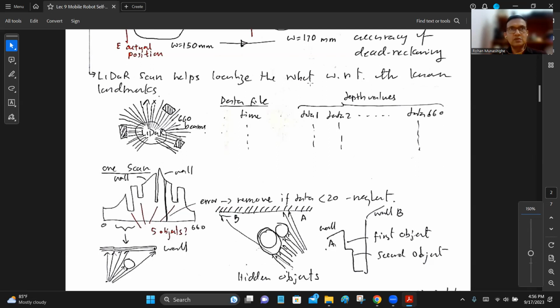To say the least. But if you want to make it more realistic, you need to get not only these coordinates but also the points around it. Unfortunately, in the case of LiDAR, you don't know the depth of the obstacle. You see only the front face. So the easiest way is to say that there are so many obstacles in line, but you combine them together as one single object. If an obstacle is long, then when you want to localize, you can use this edge, that edge. In the reference also, you can say this edge, that edge, and get one of the edges and try to localize. Because in the algorithm we are talking about vectors, and a vector means just one point. So the moment you get the corresponding point, you are done.